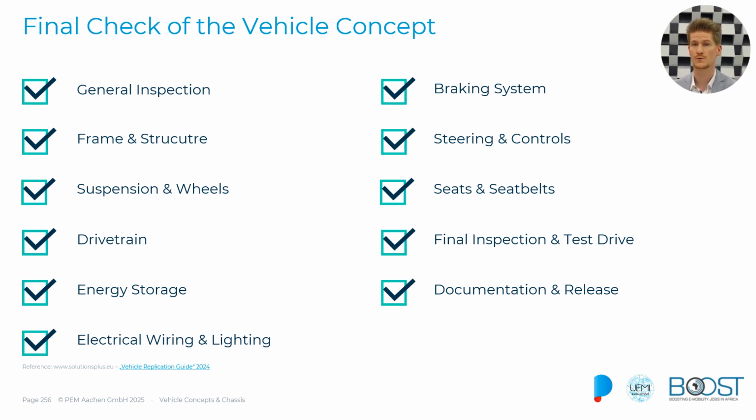Look if everything that you wanted to do is done. Look if all the parts that you needed are actually mounted, and the vehicle fits to the dimensions and the performance figures that you were calculating beforehand. Take a look at the frame and the structure. Look if this is all well done, if it's up to your quality standards, if there are any welds from the welding that are probably not perfect. Then it's the time to correct this.